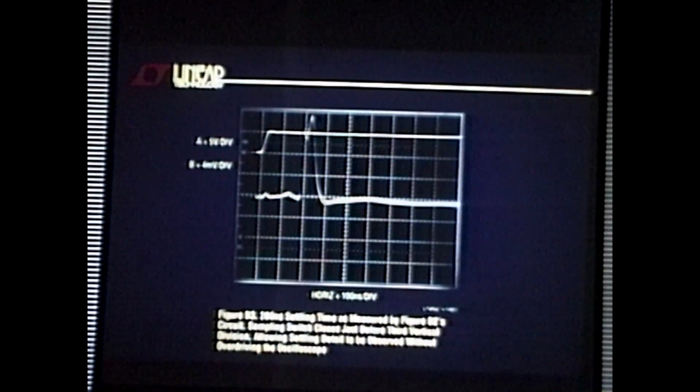This measurement's very important to people who sell and use D to A converters, and the number we were after was 300 nanoseconds. So at this point, all the marketing guys jump up and down and say, great, we've verified 280 nanoseconds. Let's sell the thing. I wasn't so happy about that. I wanted to run the test a couple other ways and get agreement, because all you ever think about as an engineer is the 747 coming in to Kennedy on a winter night, and is it really 280 nanoseconds or not?